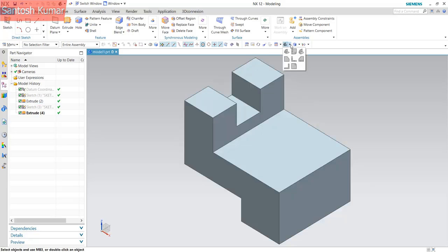If you come here, you'll be able to see all the views. You see there is a trimetric view, and you need to select the home button for that. Control Alt T is for the top view, and isometric is the N key. You select the N key, it will go into the isometric view. Correspondingly you have the left as well as the plan view or the front view, the right view, and the bottom view, and those are the shortcuts. Control Alt O is for the bottom.